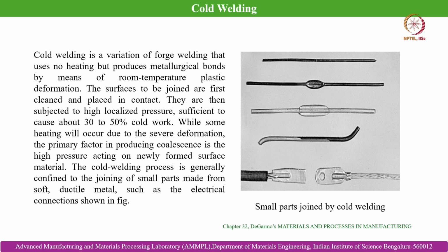The cold working process is generally confined to the joining of small parts made from soft ductile metal, such as the electrical connections as shown over here. So these are the examples of the cold welding technique.